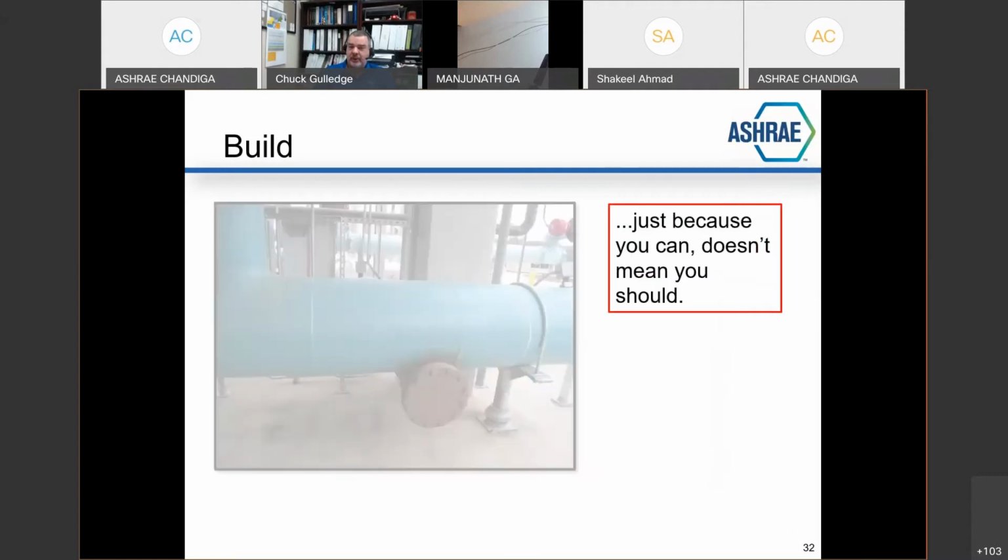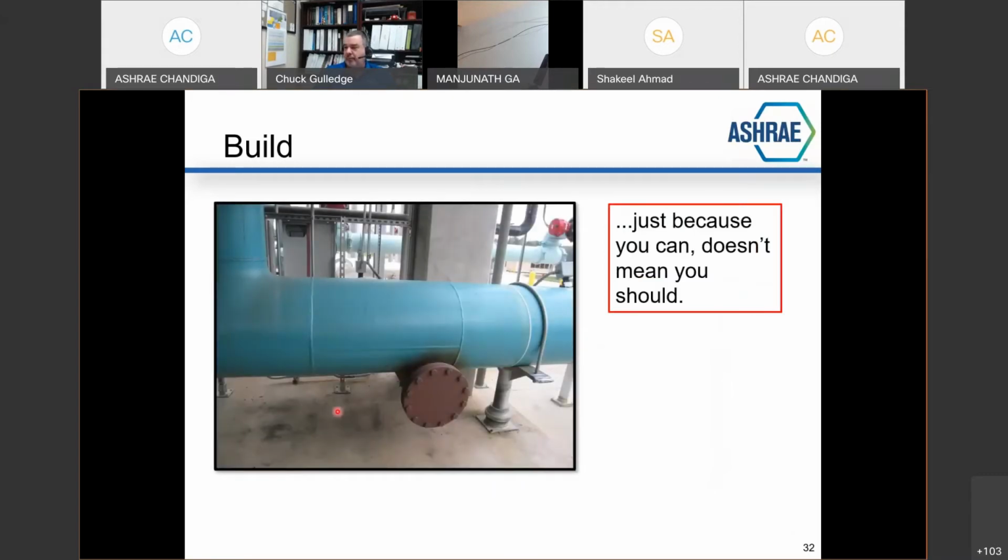Well, this is interesting. Look at this beautiful, beautiful condenser water pipe. It's about 18-inch diameter. Somebody came along and cut that section of pipe out, made a half pipe, made another half pipe, re-welded it all together, and then they stuck this really weird pipe saddle off the bottom going this way. This was a major 4,000-ton cooling tower plant for a chiller plant.